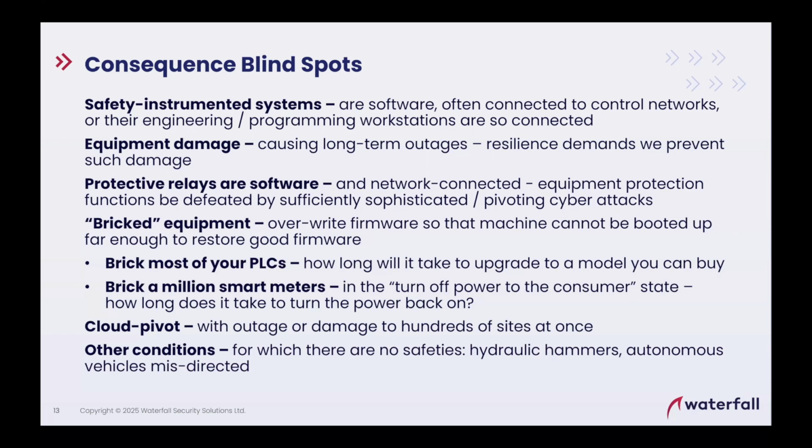If we can get into the OT network and connect to the safety instrumented system and compromise it, then in the worst case, if we can manipulate the physical process to cause an unsafe condition, the safety instrumented system fails to shut us down when that unsafe condition occurs, and now we have explosions and death. So this is a possibility. The thing most people don't realize is that most of our SIS is connected to the network.